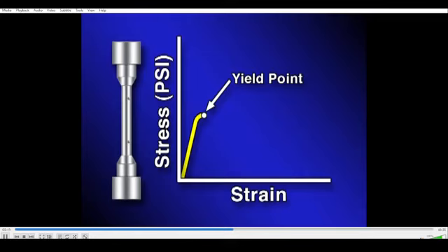This is defined as the load that causes a marked increase in strain without increase in stress. In many cases, the yield point is difficult to determine. A decrease in stress may be detected and is shown as a knee on the curve. Because of this, yield strength is more commonly used to describe the point of yielding or permanent deformation.